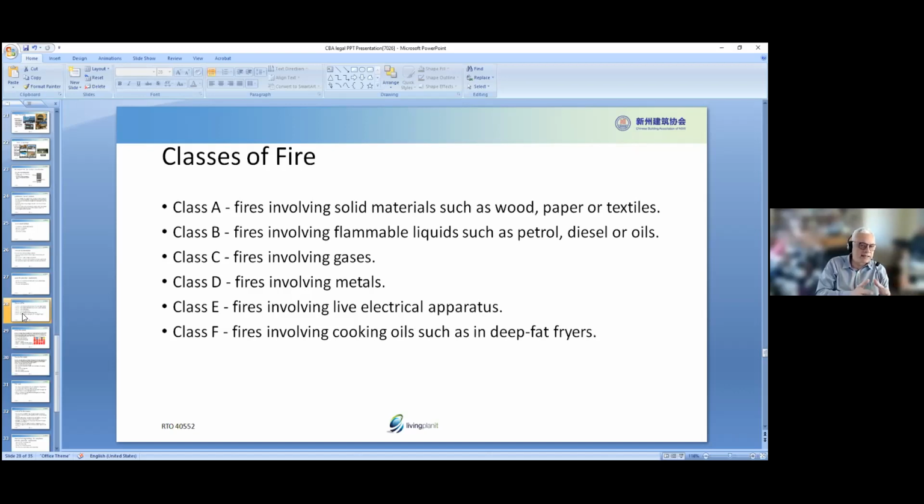So if we have a concrete wall or a block wall, that wall might be rated for 90 minutes, right? So it's rated to stop a fire going through for 90 minutes. That in itself is passive fire protection. For 90 minutes, that wall is going to stop the fire. We're not doing anything. It's just the nature of the way the wall was built. So that's a simple example of passive.